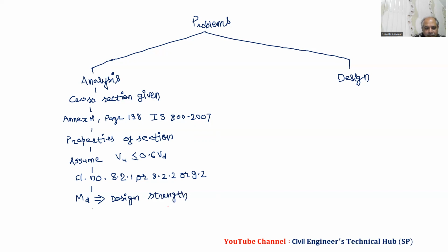Then knowing the beam, we are in position to calculate load. So we have the formula WL/4, which is equal to MU, which is MD, for a beam with concentrated load at center. And that will give us the value of W, which is acting at center.